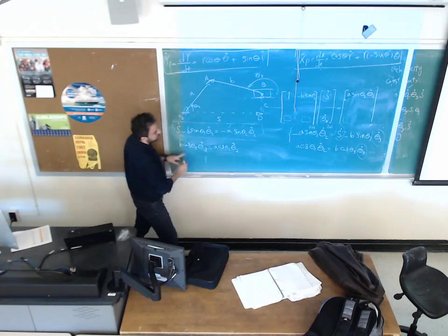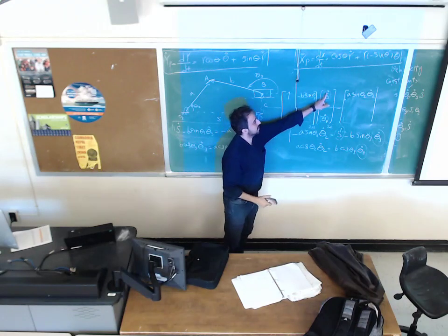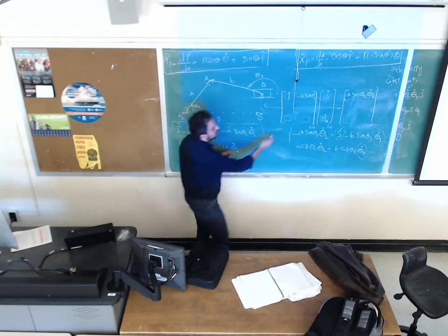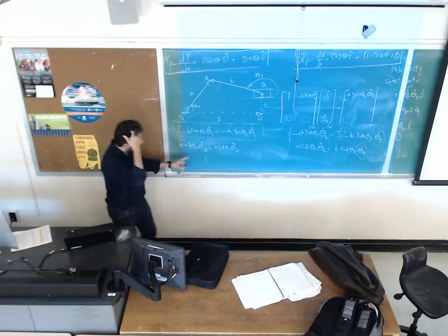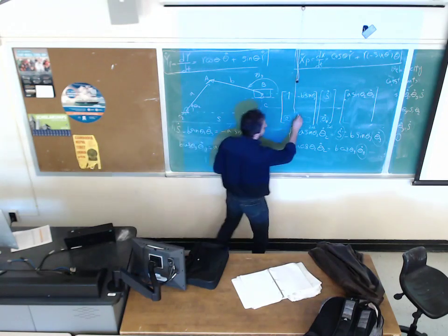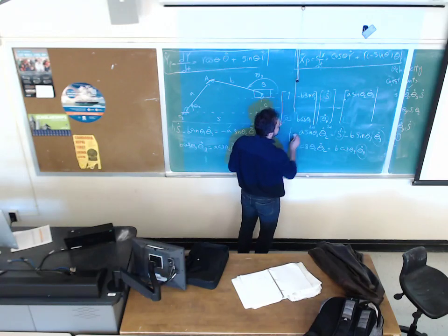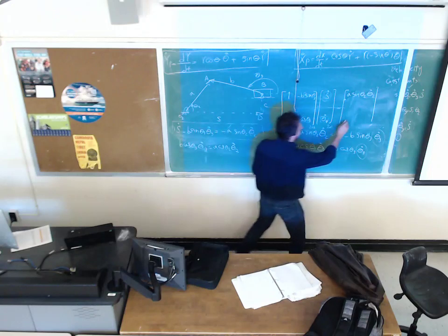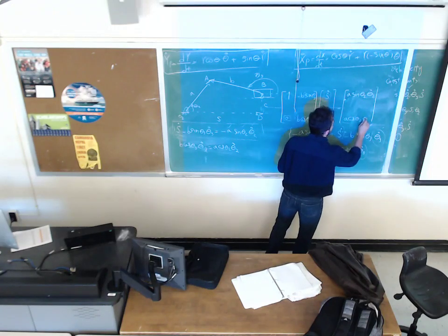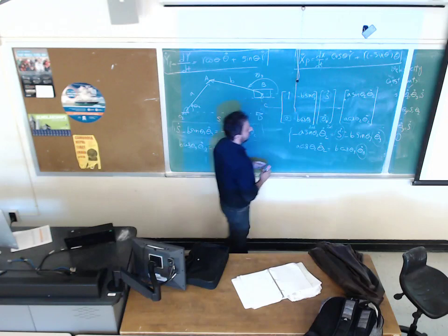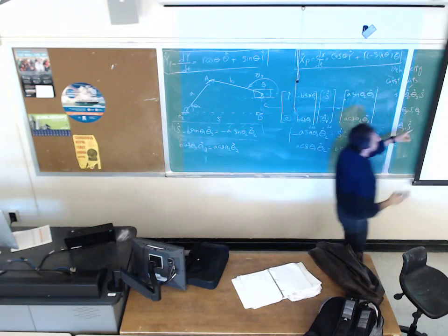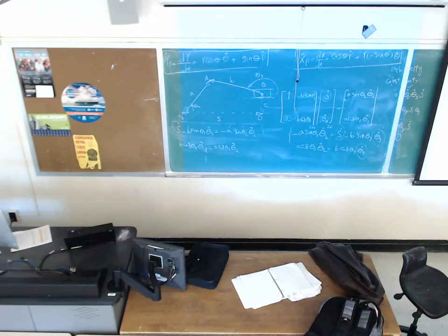Second equation. First term represents the coefficient of S dot. On the left side, I don't have any S dot, so the coefficient must be 0. And the coefficient of theta dot 3 is B cosine of theta 3. And the right hand side is the constant part, which is A cosine of theta 2, theta dot. Now I could write the system of equations in the matrix form.